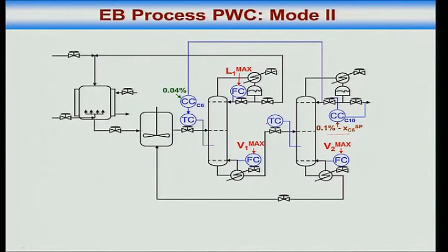Now that I have done this, I put in level controllers. Note that reactor 2 outlet valve is taken. I have to control level of recycle column bottom. The only valve available is here. So what I do is this, because this valve will get used to control level of this guy, right? So the only way to control level here is this way. The only way to control level in the first reactor is this way. Only way to control temperature of the first reactor is this way. And of course these set points must be max allowed. That's because my optimizer said so, and it makes physical sense actually. Yes or no? Okay, fair deal.